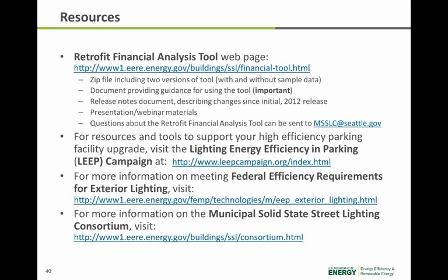And there really isn't a good hard and fast rule of thumb that if I'm using a 150 watt metal halide, then I need a 70 watt LED. That kind of gets you down the right path, but it does require analysis, and it also assumes that you're maintaining the same light levels, the same light striking that surface. So enough of that. One of the attendees asked, and I'll answer this one, Doug.